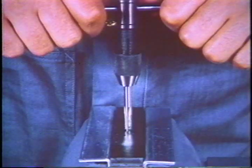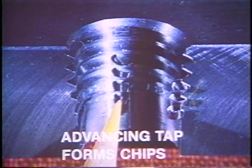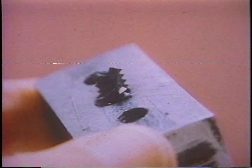The design of a hand tap demands special attention when using it. Knowing how it cuts threads will help you understand why it's used the way it is. When the tap is advanced, a series of chips are formed. It's the formation of these chips that causes tap pressure, resistance to cutting. The chips break off when you back off on the tap, so the tap can be turned forward again to cut new chips and create threads. If you don't back off on the tap frequently, the tap pressure can actually cause the tap to snap off.